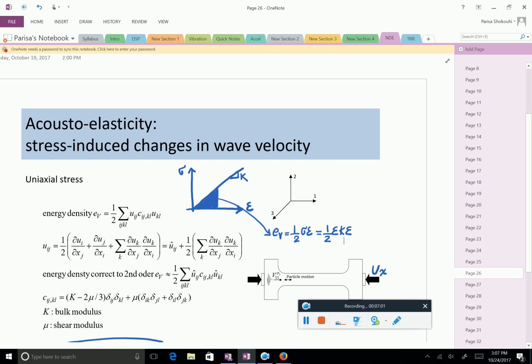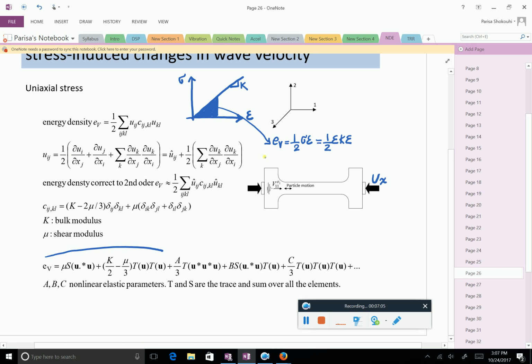So that would be the equation. And just to give you a sense of why it looks like that, in a very simple case, consider when you have sigma epsilon like that, linear. If you write the area, it becomes 1/2 a strain, a stiffness, a strain. Now in tensor form, in the general case, 1/2 a strain tensor, elastic tensor, a strain tensor.